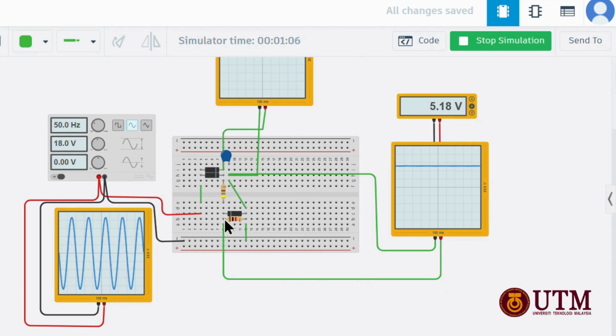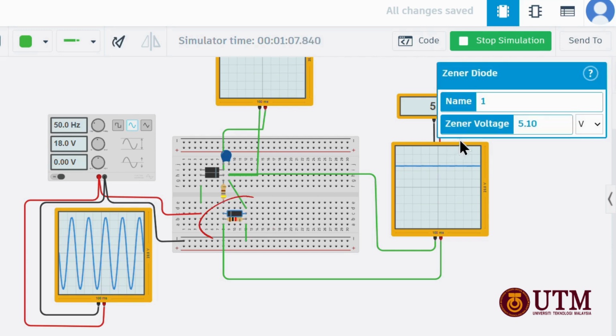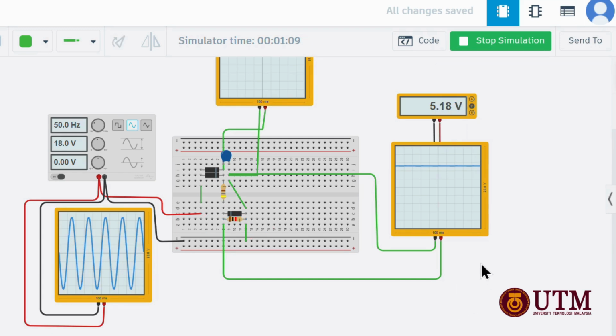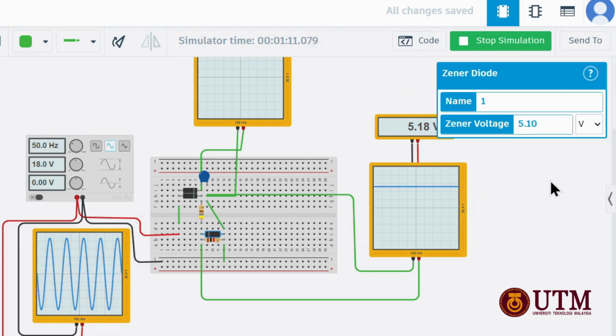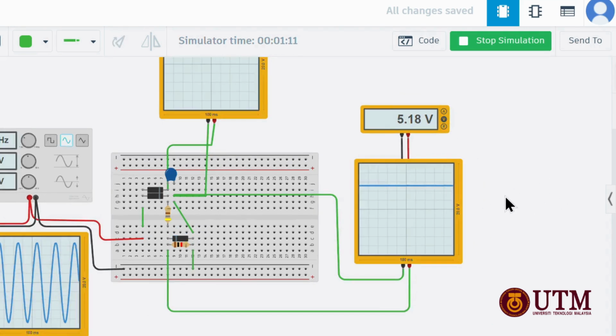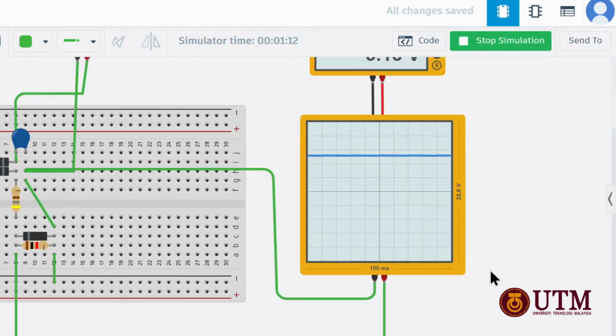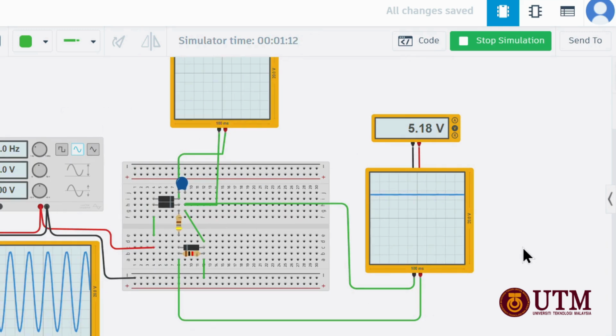Finally, the power will reach the zener diode and also the 1k ohm load resistor. The zener diode will act as a regulator, whose job is to lock the voltage at 5 volt. So even when the load resistor uses the power, the zener will keep the voltage from changing.